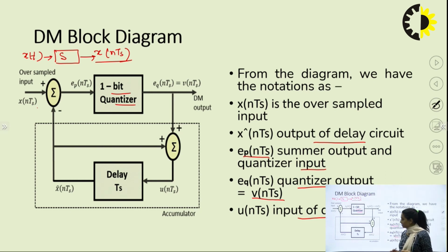So what basically happens is, if I have this signal, I represent it with the present sample value taken here, which is compared with the previous sample, and if it happens to be a higher value, the step size will be raised by plus delta, right?